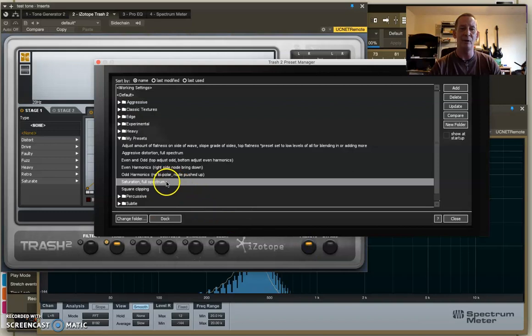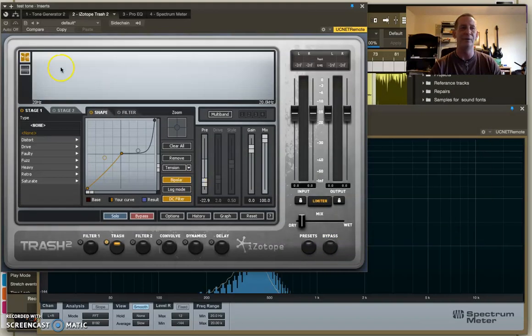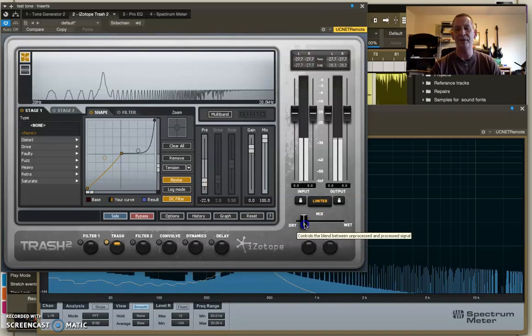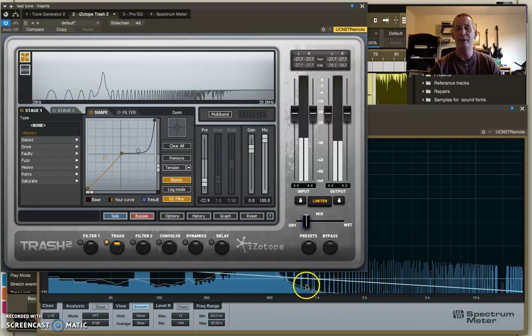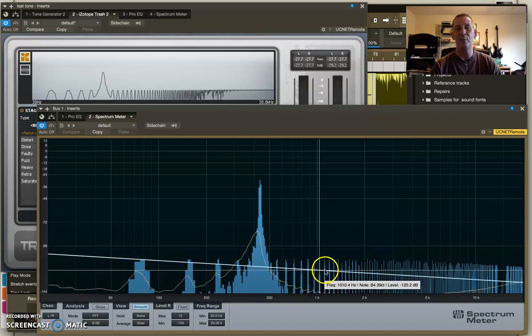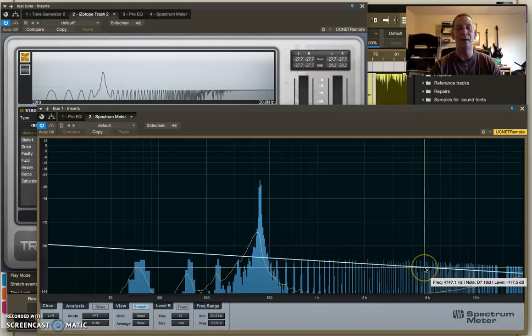So, you see noise going across the spectrum, and if you look at saturation, if I go in here and choose full spectrum saturation, you can see the difference. If I turn it on, it's real obvious what the difference is. If you look at it, saturation is more musical because you can see looking across the spectrum that there's separation there, even and odd harmonics, all kinds of harmonic content that's nowhere near as dense as noise.